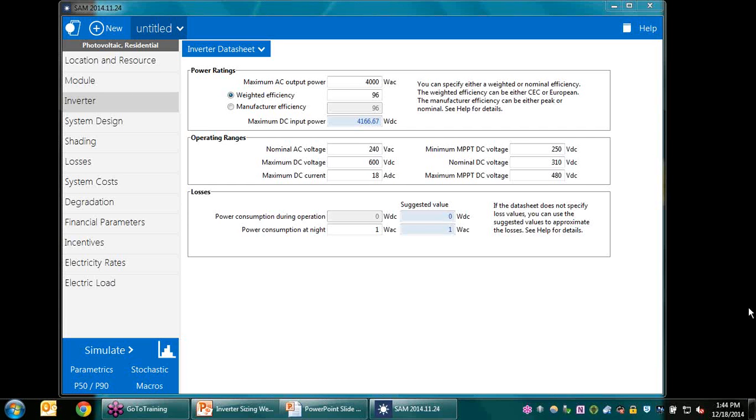For instance, if the DC generated by the modules is 36 volts per module, and then if I put 10 modules in series, I will have 360 volts DC. And the AC is the output of the inverter, like 240 volts. And this will give the ratio in the end, dividing one by another.